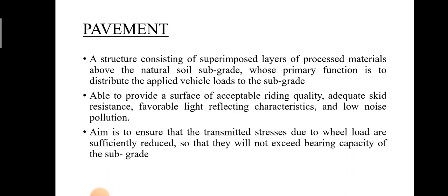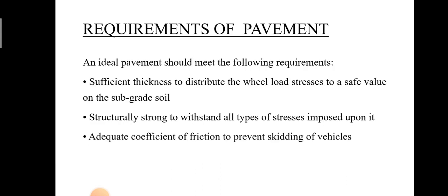And a pavement should be able to provide a surface of acceptable riding quality, adequate skid resistance, favorable light reflecting characteristics, and low noise pollution. The aim of a pavement is to ensure that the transmitted stresses due to wheel load are sufficiently reduced so that they will not exceed the bearing capacity of the subgrade. And these are the basic requirements of a pavement.